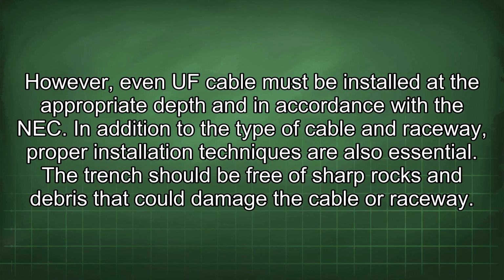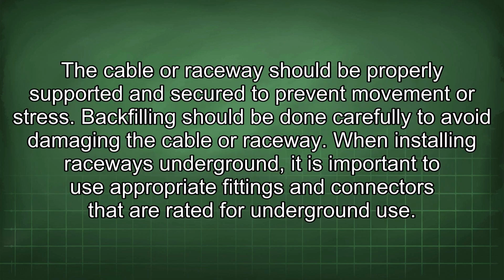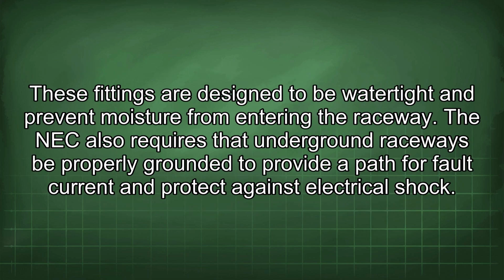In addition to the type of cable and raceway, proper installation techniques are also essential. The trench should be free of sharp rocks and debris that could damage the cable or raceway. The cable or raceway should be properly supported and secured to prevent movement or stress. Backfilling should be done carefully to avoid damaging the cable or raceway. When installing raceways underground, it is important to use appropriate fittings and connectors that are rated for underground use. These fittings are designed to be watertight and prevent moisture from entering the raceway.